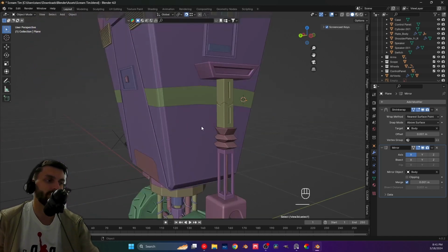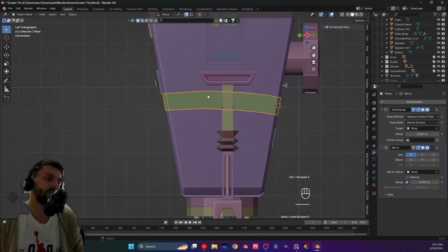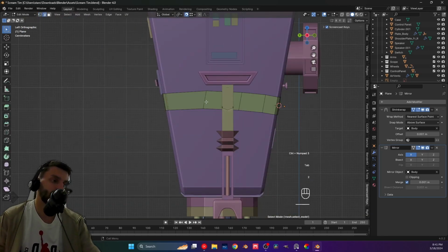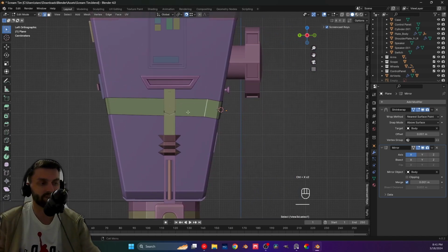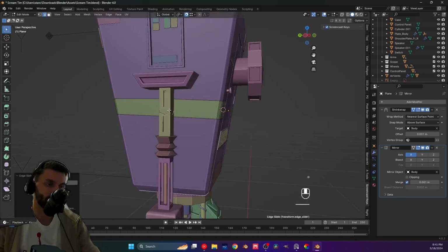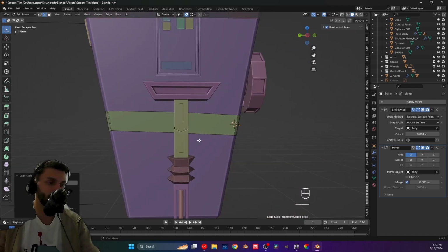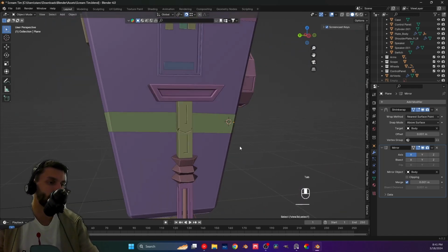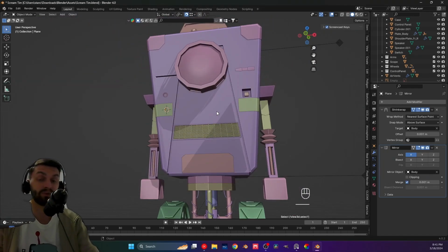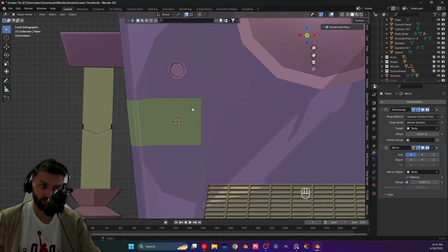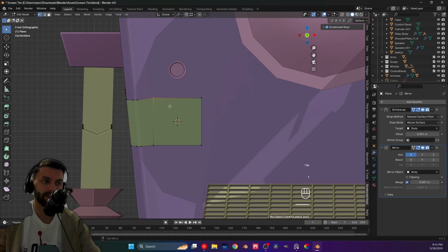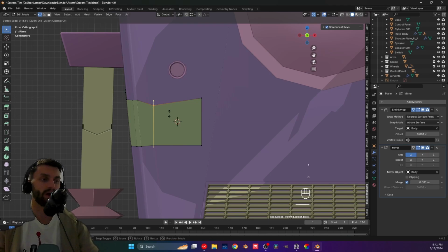And now we have that band, which is right over here. It's just waiting to be textured. It's also low poly, so we always love when we hear that. We can actually leave it over here, but we basically have a very low poly band over our body, which is really okay. And what I do advise you to do now is deactivate snapping, because now we don't need it, and play with your geometry to make it look how you want.